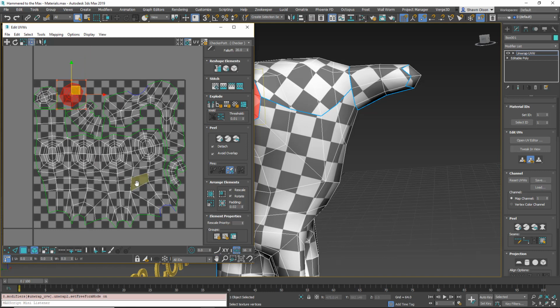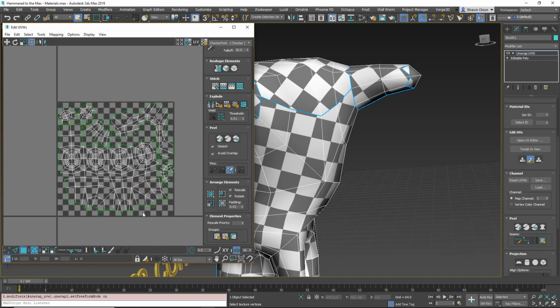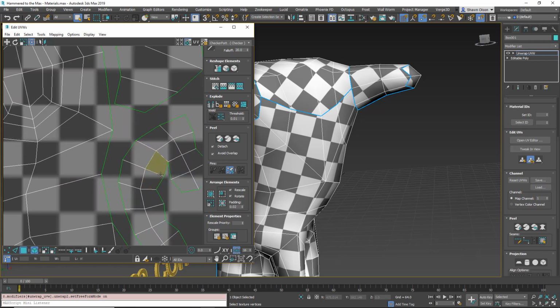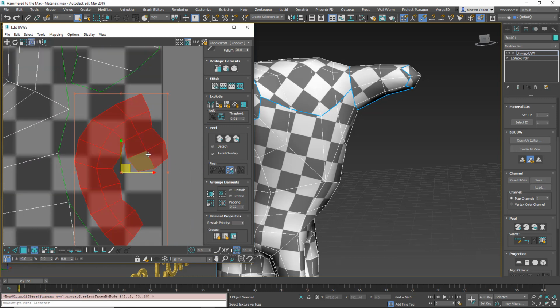So what we've done here is we've used up a little bit more of the texture space. Any of these gaps between the islands thus becomes wasted space, because in the end, the whole point of unwrapping like this is it allows you to bake your textures down into a bitmap, and that's what you need to do to get into a game engine in many cases. We got this sticking out the side here.